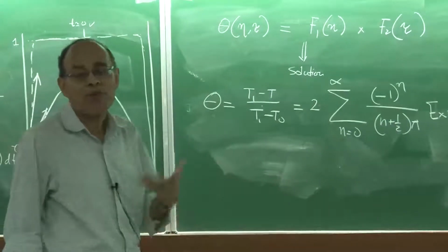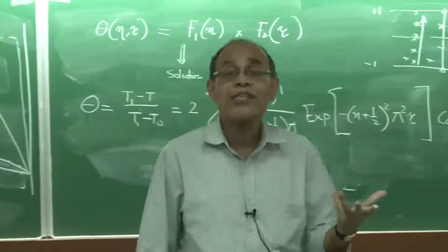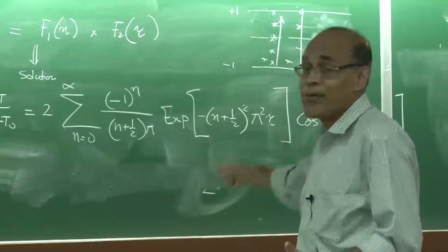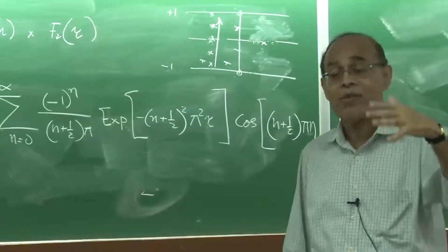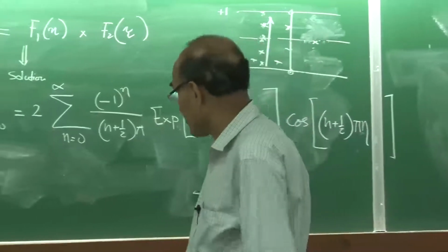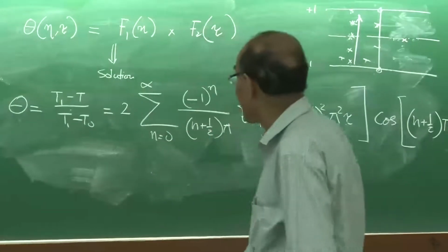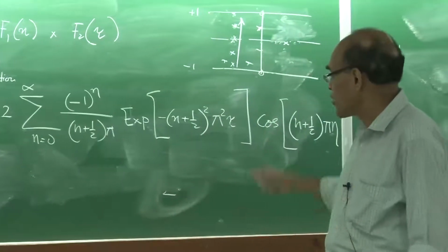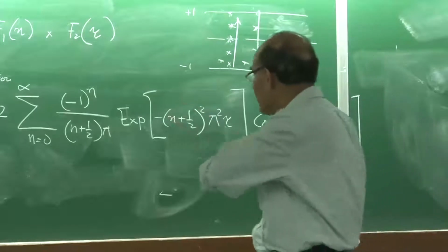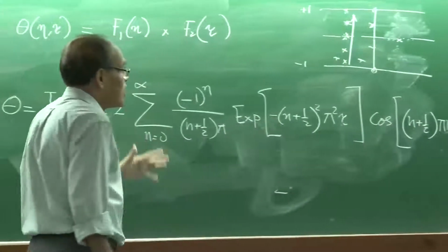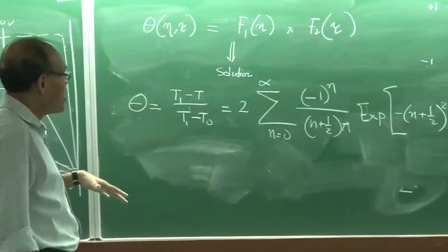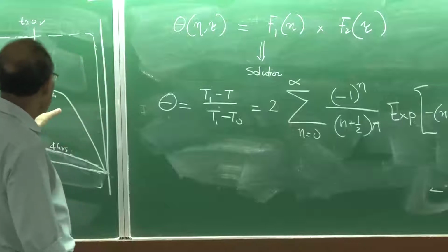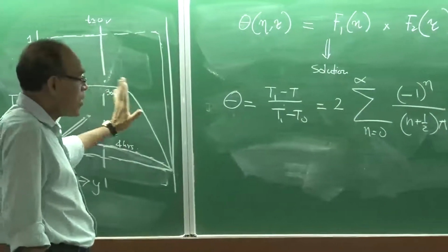An equivalent problem can be derived, or solved, for example, in a cylindrical coordinate system, and in that case the solution is not going to be a summation series, but you will get solutions with a characteristic Bessel function. So, the Bessel function solution comes from cylindrical geometry, and you can see similar kinds of solutions in the textbook that I have. But those would take much longer to introduce, with all these particular cases. So, therefore, I will stop as far as unsteady state heat conduction in 1 dimension or 2 dimensions is concerned.